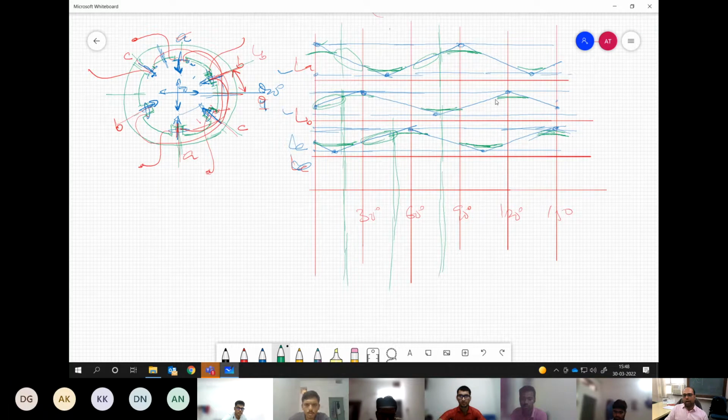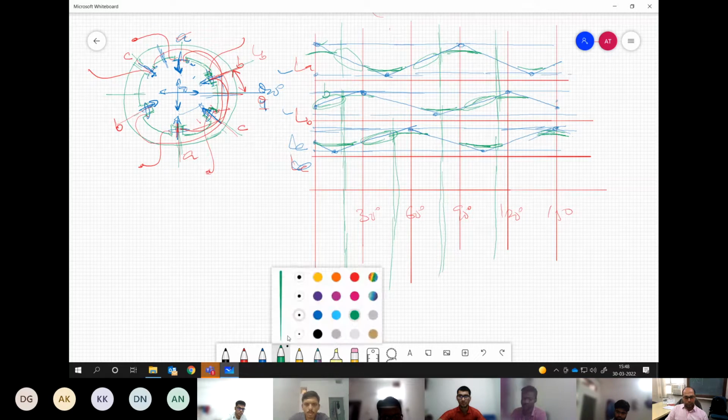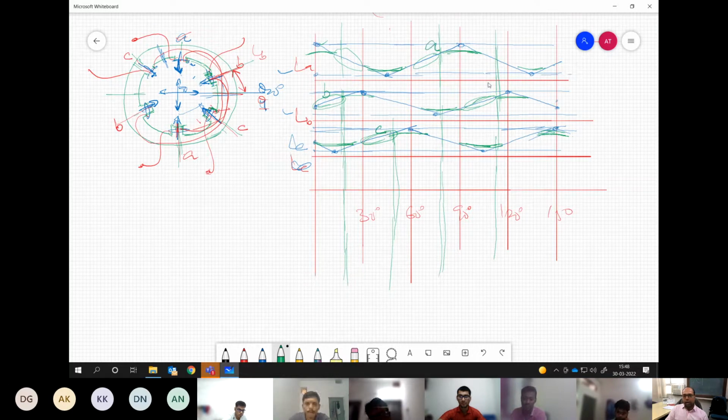That linear portion we are trying to take out. Again, we will have that kind of slope here. So if you see that it's coming in sequence, positive for B, then positive for C, then positive for A, again positive for C, and then this positive for C. This we are trying to generate positive torque.